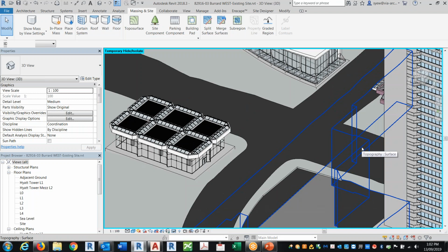Pretty easy, pretty straightforward. So to create the roads, as you say, over top of the tunnel, you would use a slab as opposed to the railing tool? Yes, I will use slope slabs. The railing tool will fail, because the pads, it does not respect. The railing only respects it if there is a surface on top. If there is no surface on top, it's just going to fall flat, because it just follows whatever the pad's doing. To host on something, yes, something that is a surface.